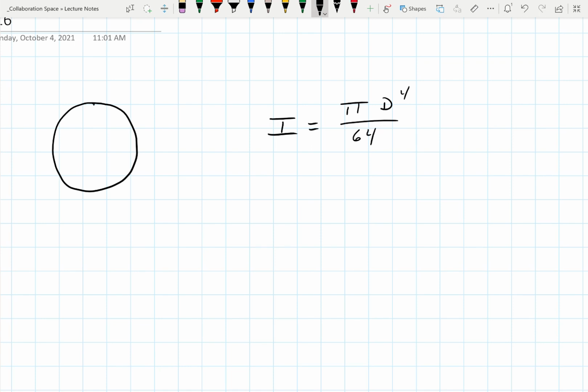But there is a value that's pi d to the fourth over 32. It's the polar section modulus when we do torsion. Well, that would be J. All right. Area, as long as we're at this. Area of a circle, folks.